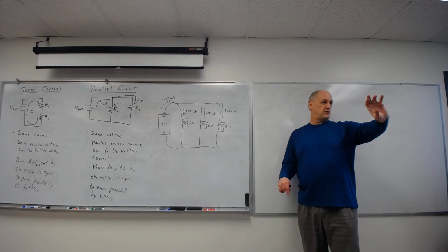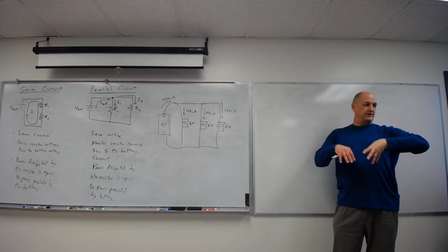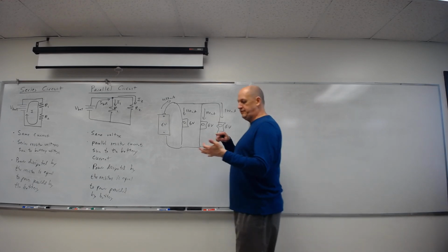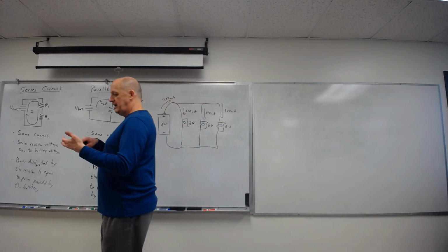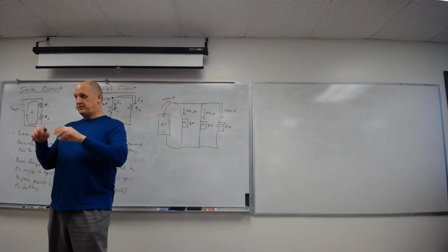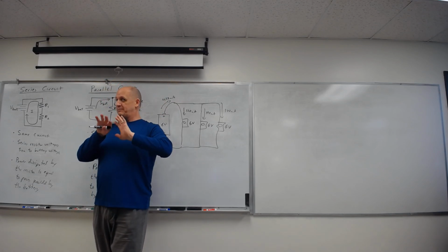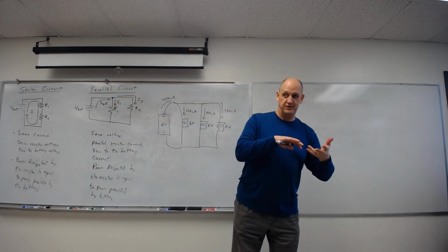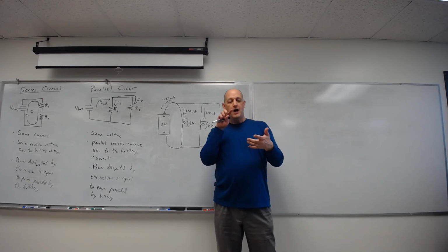Okay, so you hook the resistor up, you measure voltage and current, and you start putting them in a table, and you can plot them. Yeah. And I have some things on there. I'll have measured voltage, measured current. You should measure your resistance with the ohm meter, just completely out of the circuit. Don't measure it when it's connected to power, because it won't work. That'll hurt stuff, potentially. Probably just won't work right though.